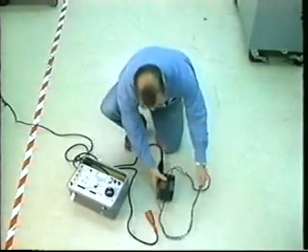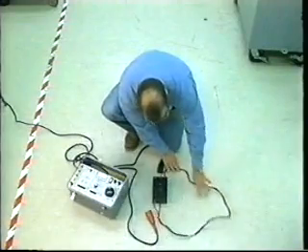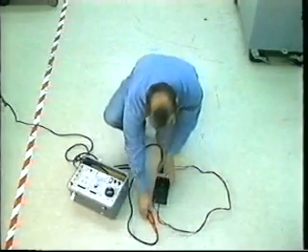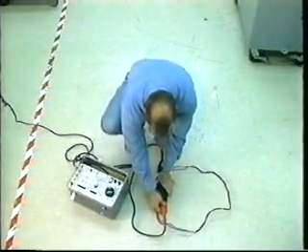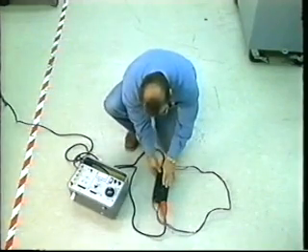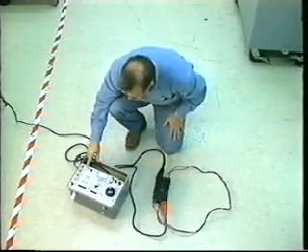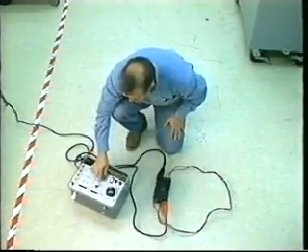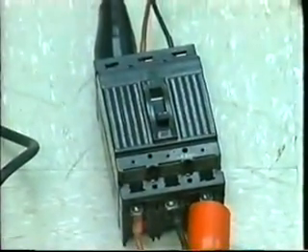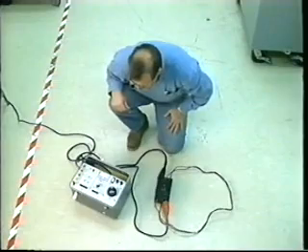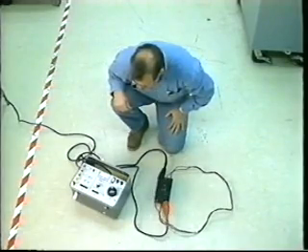A rated current hold-in test is an optional test that's performed only if there is a possibility that the circuit breaker is unable to carry the rated load. This test consists of mounting the circuit breaker in free air with its poles connected in series. All cables, including the series jumpers, must be of proper ampacity and be approximately 4 feet long. When rated current is applied, no tripping should occur if the circuit breaker is operating properly.